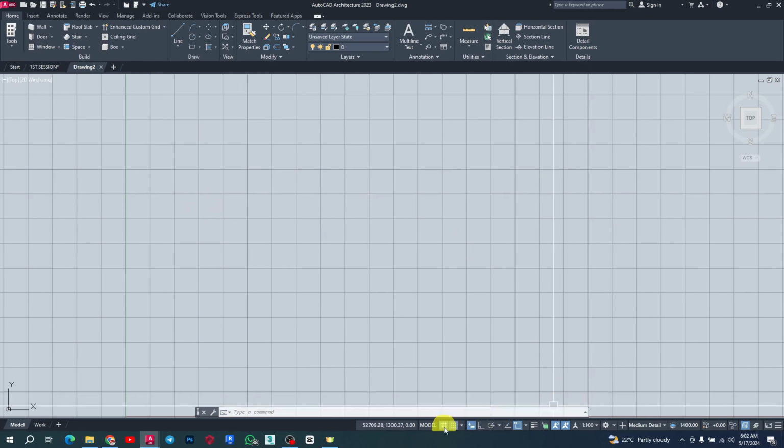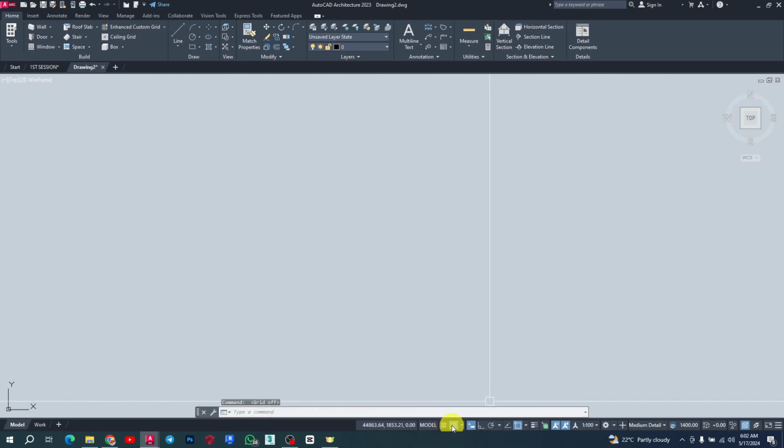Okay, so I'm going to remove this grid, because I don't like working with it. If it's something you like working with, you can just leave it there. I'm going to take out my grid and also turn off snap to grid, snap to drawing grid, because it will make my arrow flicker. I want to take that one off, and then leave my orthogonal reference on, so it goes only in the X and Y direction. You don't want to make errors by drawing lines that are not perfectly straight, vertical or horizontal. So you want to change that one.